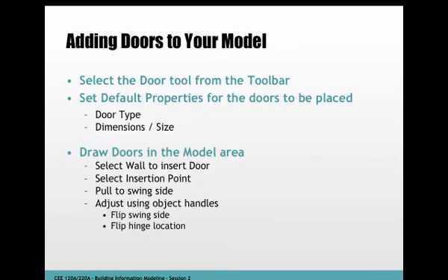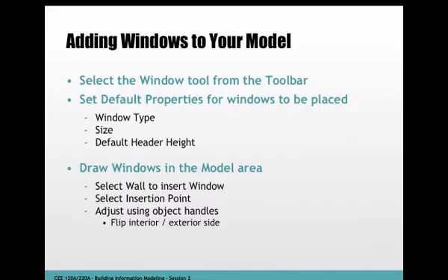And then there's this whole issue of doors and windows. Oops, I guess in the slides I was doing doors first. Doors I tend to think of as being simpler because you don't have to worry about the sill height. They typically just sit at 0, whereas with windows, you have to worry about the sill height and the head height. But either way will work. So a little about doors, creating new door types, and windows. That's sort of where the slides are.